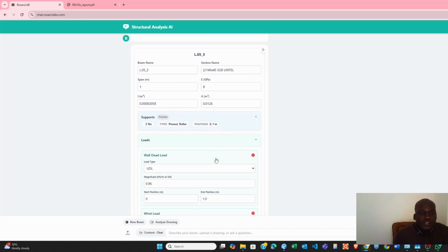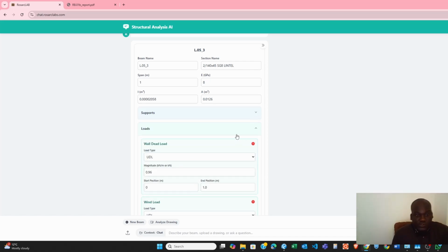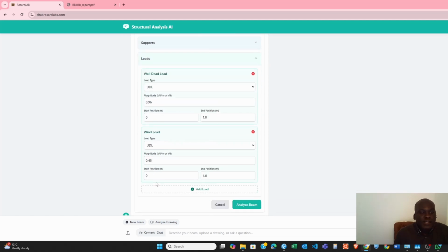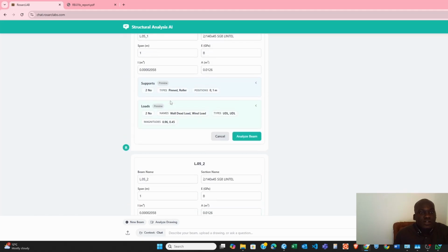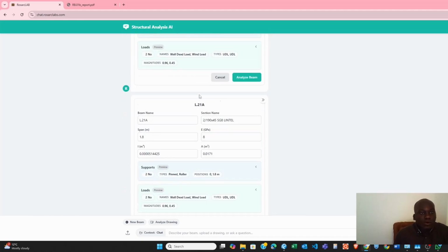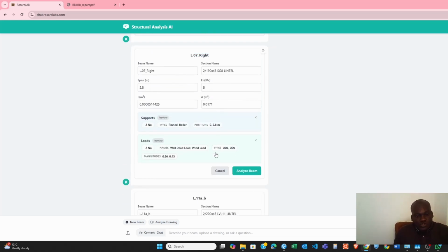That's it here. So this is just a preview. If you click on it, you get the more details into the system. So this is being rolled out as a simply supported beam, and that's what the system defaults to. So yeah, you can see the loads now added to each. So there's the preview to each lintel. You can do this for each parameter. You can say, for example, you want the floor beams to be fixed support, I need to change that there. So just doing things like that, and that's the beauty of the system.